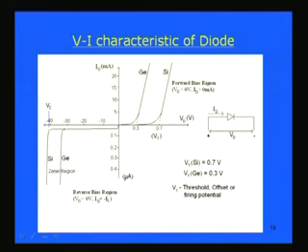The power dissipation capability of the diode should be very high. Under normal diodes, if we apply a very high reverse bias potential, then it may not be possible for the diode to sustain that high power being dissipated. So, you generally do not apply such a high potential to a normal diode, and for that, particularly for the Zener voltage, Zener diodes are used, which can withstand this high power.